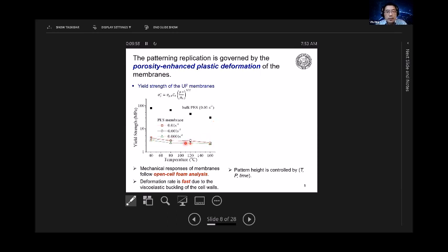These are the membranes that we measured under different deformation rates. Now you can actually plastically deform the membrane with pressure of about 2 to about 4 megapascal. That's precisely what we used, and we did extensive mechanical analysis of microporous ultrafiltration membranes. Basically, what we found is that the mechanical response, including yield strength, can be reasonably well described by the open cell foam model, which people have developed for 20 years, used for larger kind of styrofoam essentially, right? But here the pores are tens of nanometers.